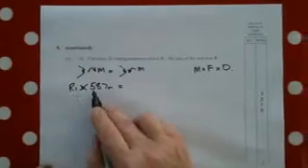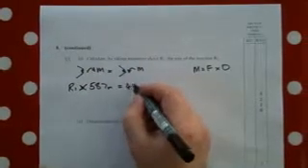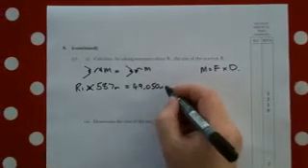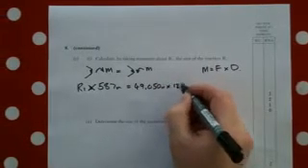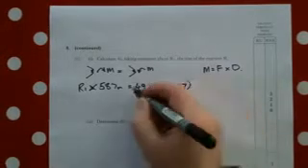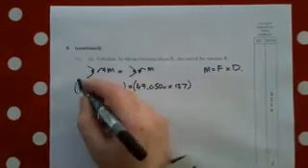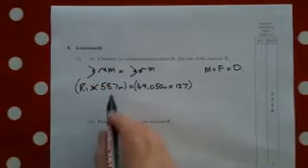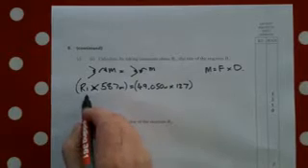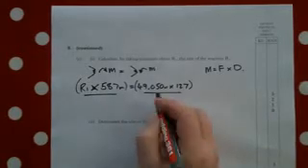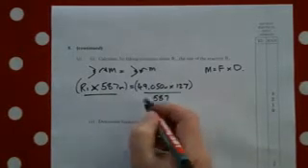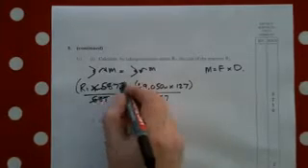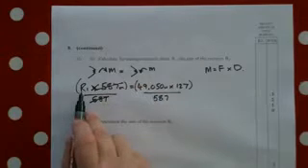So R1 times 587 is equal to 49,050 newtons multiplied by 127. So that's one side of the equation and that's the other. Now we want to get R1 on its own, so we need to transpose the formula. In order to do that, we simply divide both sides by 587. These two cancel each other out, which leaves R1 on its own.